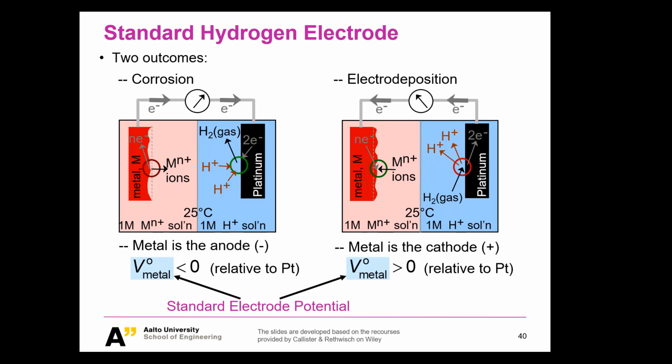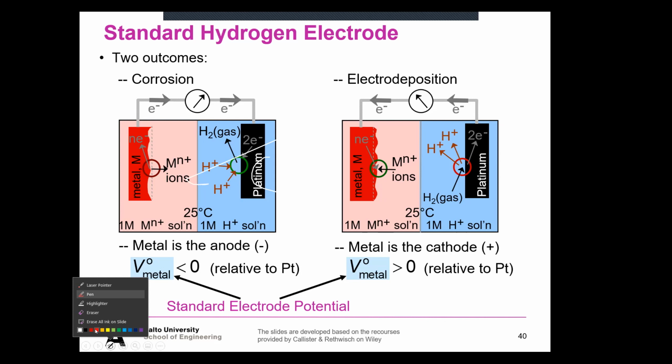For example, if we take a kind of noble metal, platinum, on one side, and you take other metals on the other side, if the potential of your metal is smaller than platinum, they're basically going to lose electrons. And here you see your material is losing, because part of it is becoming ions, and that is so-called corrosion.